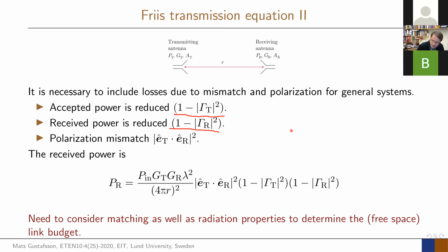And you can have a polarization mismatch, which means that one antenna points like this, and the other one points like that. They are not co-polarized, these dipoles. It should be like this. If they're like this, they don't work. And now you have a Friis transmission formula that includes also these cases where you can have mismatch in the antennas. And that means we just have to add these terms that sit there. We add that to the Friis transmission formula.